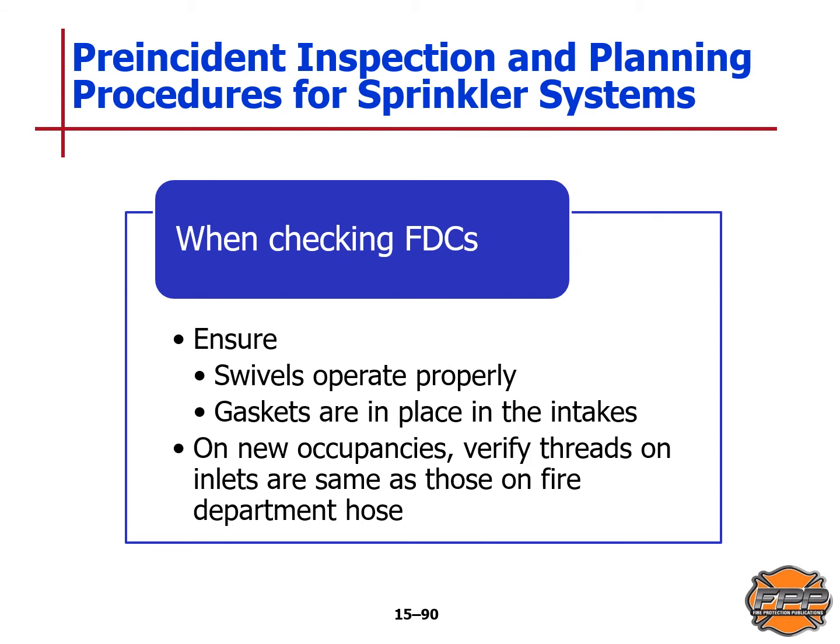When checking fire department connections, ensure that swivels operate properly and gaskets are in place in the intakes. On new occupancies, verify the threads on the inlets are the same as those on the fire department hose.